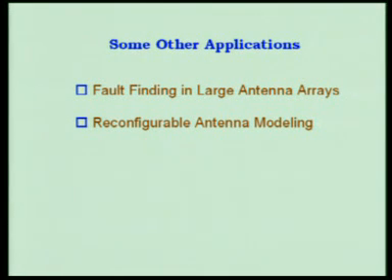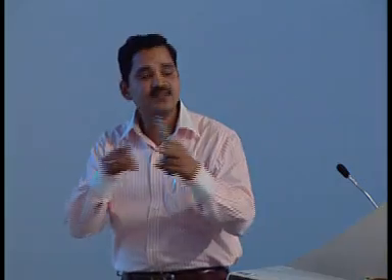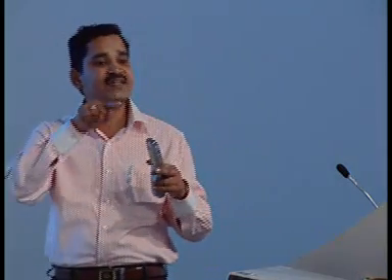So now again there are two different problems. First thing is, from the base station itself, you have to find out which particular antennas are not working in that array. Second thing is how to change the weight values or the excitation of the antennas which are in working condition, so that the same radiation pattern can be restored. That we have to do from the base station itself, right? So we tried to solve that one.